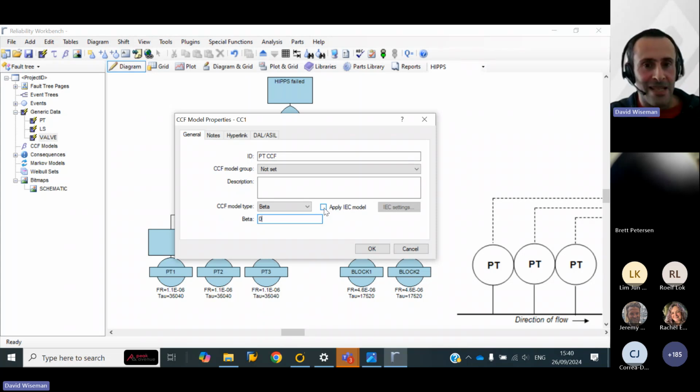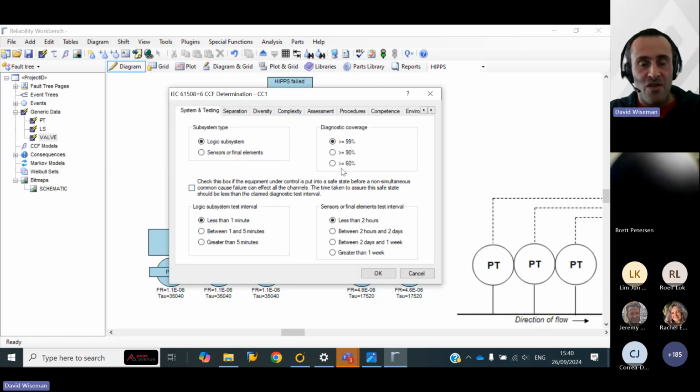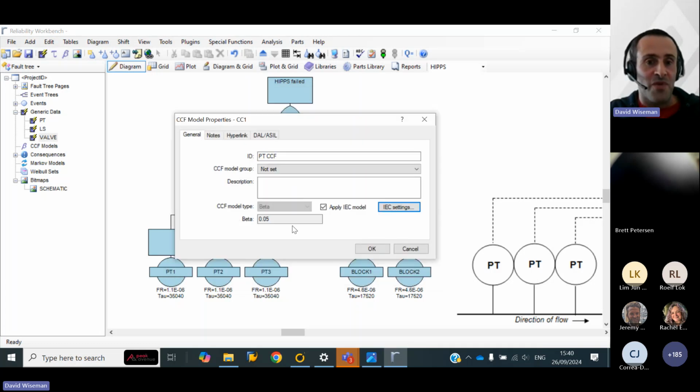And when you get to the end, based on the answers you've given, you can calculate what the common cause failure beta factor should be. We've basically put that into code so you can turn that on, go through all of those options, and when you've selected all your options, the program gives you the common cause failure factor based on that. I might even keep that actually because it's the same as the value I want to use.